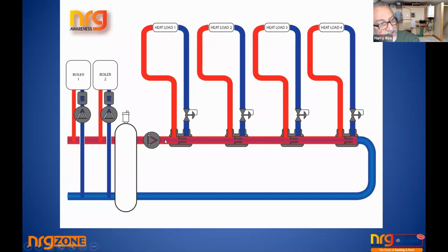They even have a system, or they use that system, where they don't have zones, but they want to have, say, one pipe system. And you might say one pipe systems are a thing of the past, but think about this. If a heat pump or a condensing boiler needs a maximum temperature drop, you're trying to increase the delta T, the difference in temperature from the flow to the return, it actually is a very good idea to consider taking the heat, strip some energy away, go on to the next one, strip some energy away.